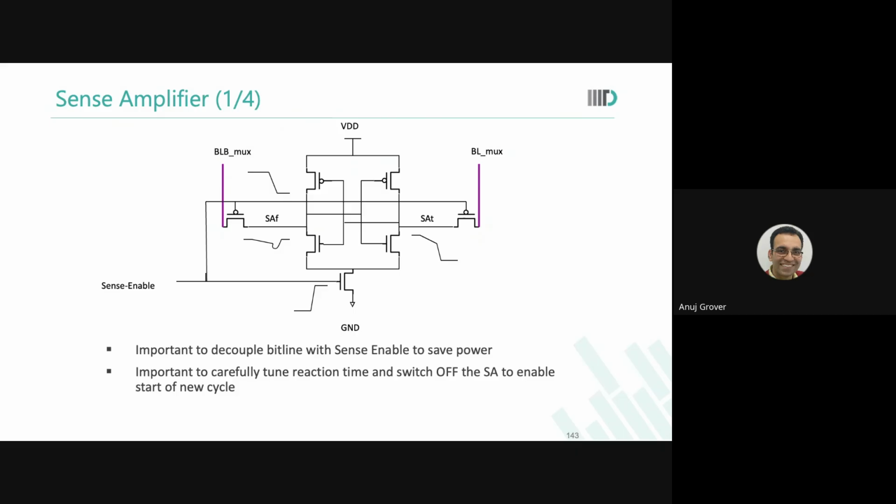Why do you need a latch? Because to reset the memory again, you will take sense amplifier nodes back to VDD. Then all this 0 and 1 on SAT and SAF would be lost. But memory still needs to drive the output driver. Old output has to be held until the new output comes. Is it not? So you need to latch the output of the sense amplifier somewhere.